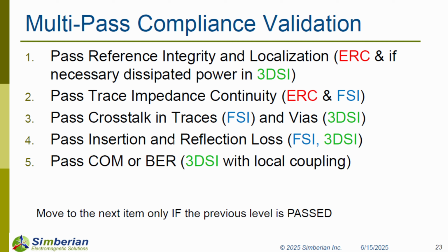This is reflection loss and insertion loss. Preliminary analysis or low data rate analysis can be done with FSI, and for high data rates and the final check, 3D SI analysis is required. And then most of the SerDes standards like Ethernet, OIF, and now JEDEC, are based on channel operating margin metrics, so that requires definitely 3D SI analysis.